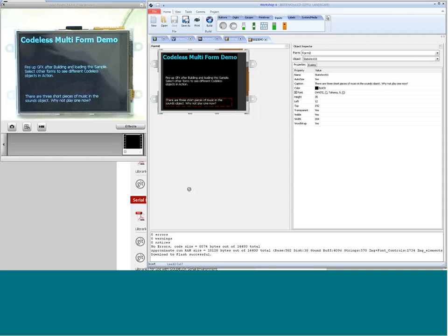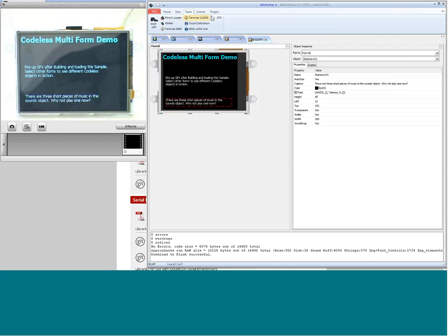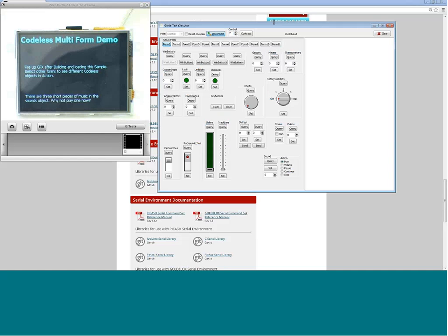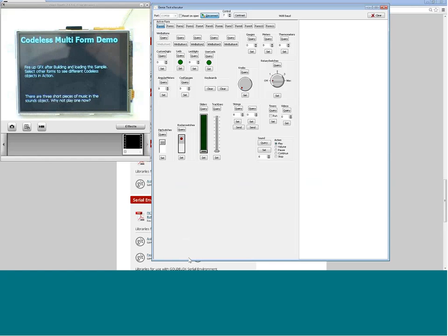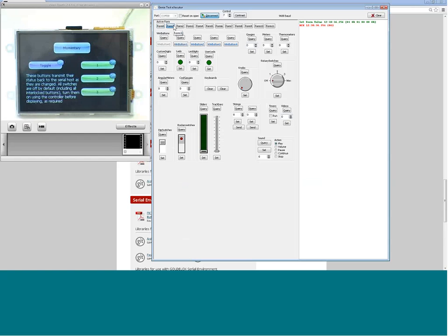And now I want to present to you the GTX feature of Visi Genie. You can find it under Tools and here GTX. So this is showing all elements you used in your environment. You can enlarge this display so you have lots of space for more buttons and gauges and knobs and everything. But here you can see serial commands going from the host, which is my computer, into the display. So I can change the form, and you see what serial communication is going back and forth.